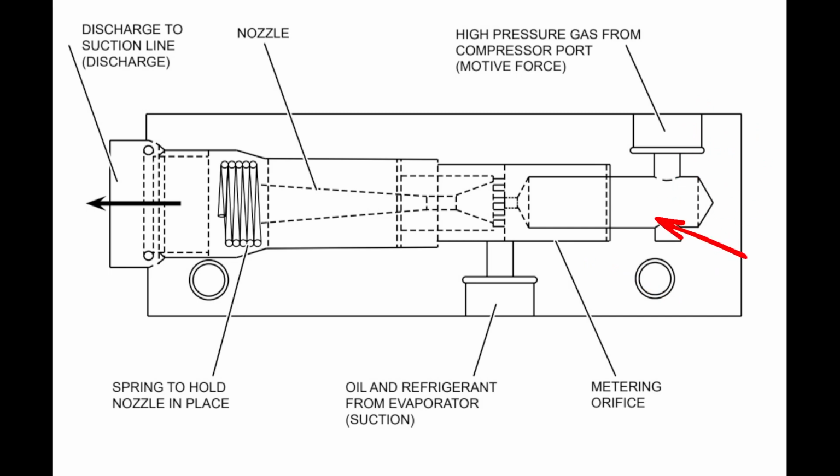So you'll see a little bit of variation there, but the overall fundamental internal concepts of what's happening here are true, and the fundamental engineering of what a jet pump or an eductor is doing doesn't change based off of the system. It's just where it's located and exactly where it sends the output to that really changes the most.